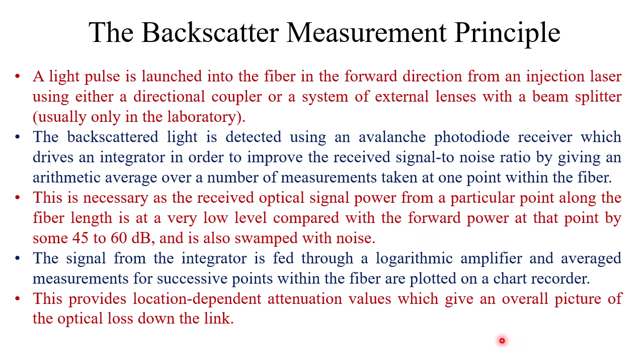A light pulse is launched into the fiber in the forward direction from an injection laser, using either a directional coupler or a system of external lenses with a beam splitter. Usually only for laboratory purposes we use a beam splitter.